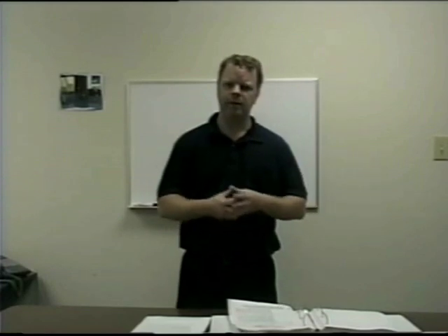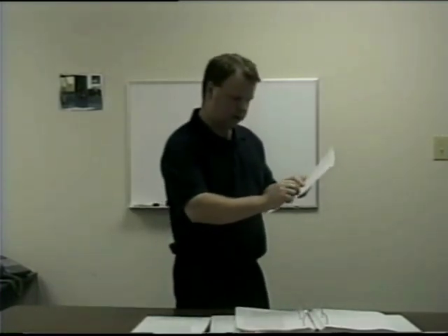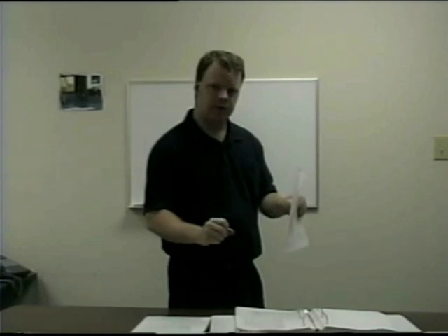We're going to tell them roll roofing has to be stood on end, has to be kept free of contact with earth, with soil, and moisture. So what happens if his material gets wet? We mark it with spray paint, make him remove it from the job. So if it gets wet, we make a note here, material was wet. We get a separate sheet, we staple it on there, and say subcontractor was notified material was wet, material was marked with spray paint. Subcontractor came on this date, removed material from job.